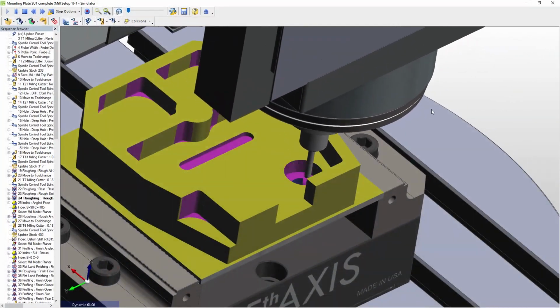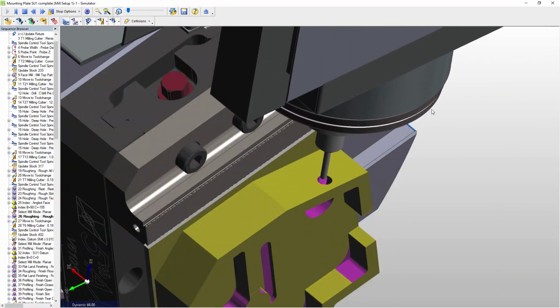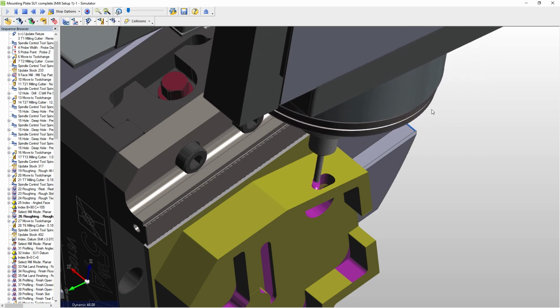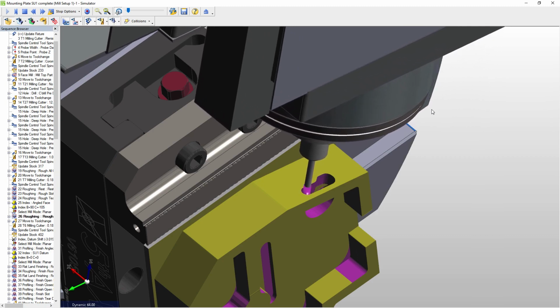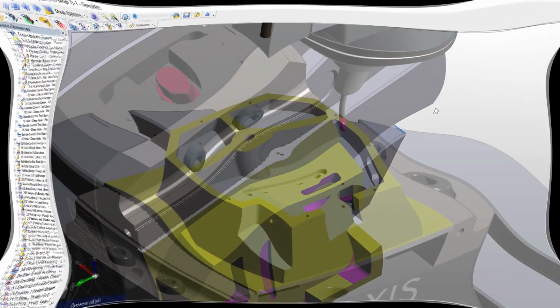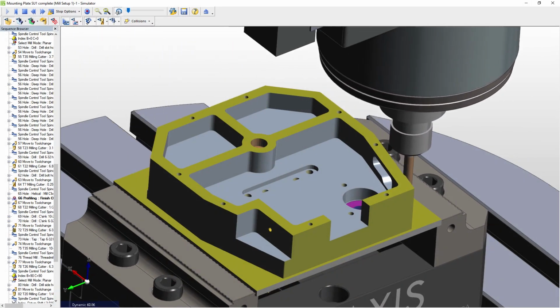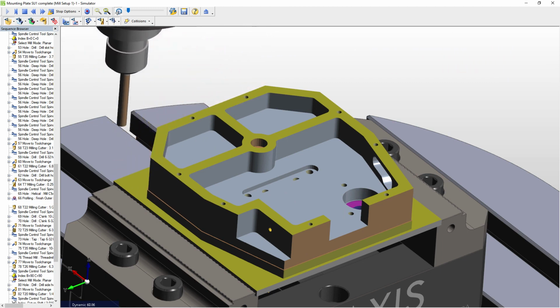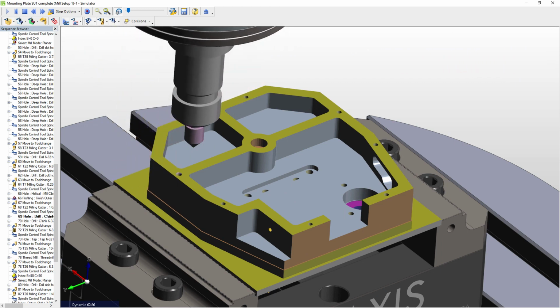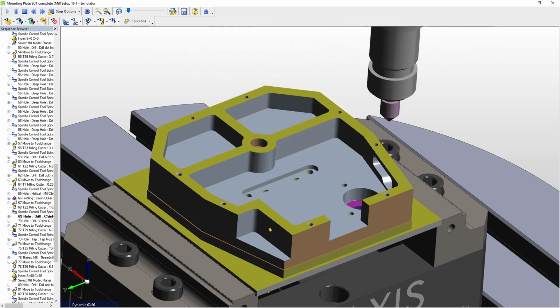As we look further toward the end of the rest roughing, we can see all the areas where this tool has removed material, and then on to where we index and machine a smaller pocket that tool is well suited to. Following roughing, we move into finishing work, both counterbores, profiles, outside walls, pockets, floors, which also includes hole drilling.